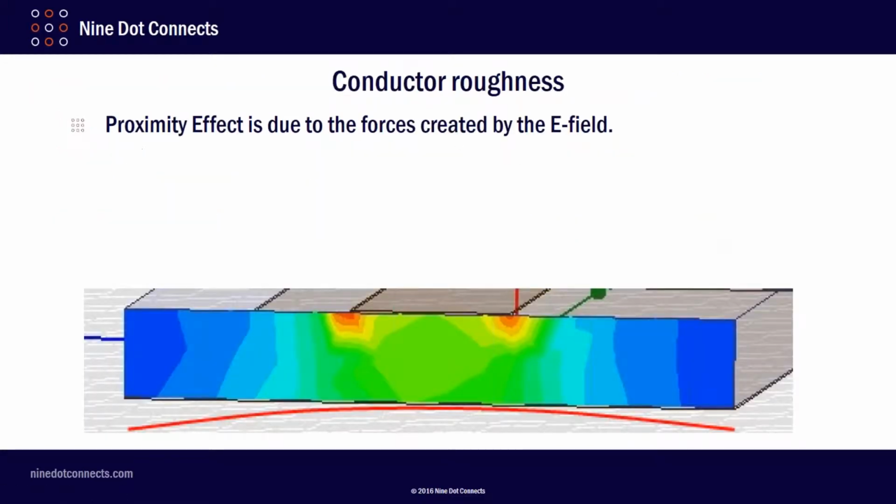If you go back to what we were talking about before, and this is a very thin piece of copper microstrip, when you're thinking about all the electrons and their density in this copper, most of them are going to be on the very bottom, that is the part that is glued to the substrate. Not only is it going to be a majority on the bottom, but they're actually going to collect more in the corners.